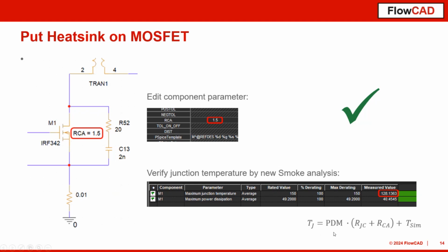The power dissipation is happening because of the switching losses, and you also have the losses when the current flows through this transistor. That is mainly controlled by a resistance called RDS on. Just look in your database if you possibly find a part that has some better electrical characteristics for your circuit.